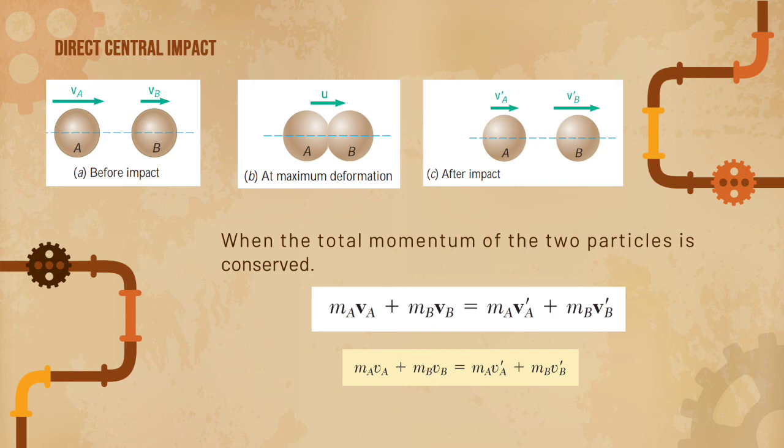A period of restitution will then take place, at the end of which, depending upon the magnitude of the impact forces and upon the materials involved, the two particles either will have regained their original shape or will stay permanently deformed. Our purpose here is to determine the velocities v'(A) and v'(B) of the particles at the end of the period of restitution.